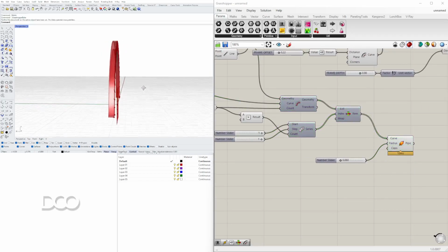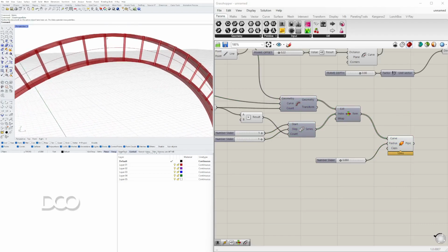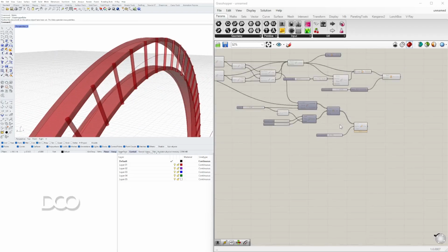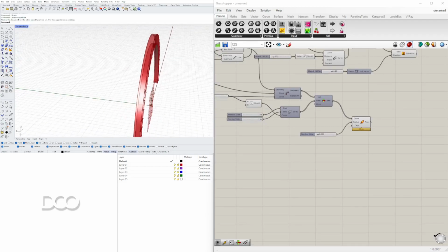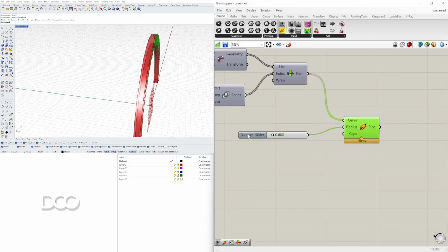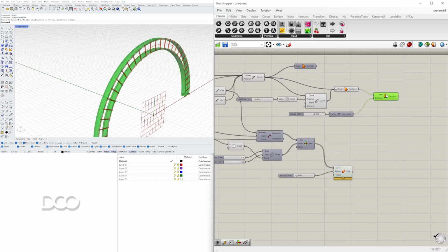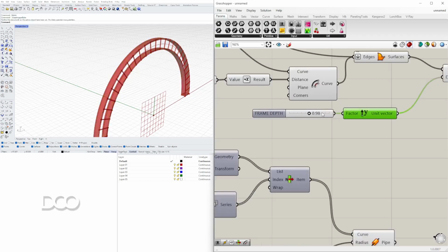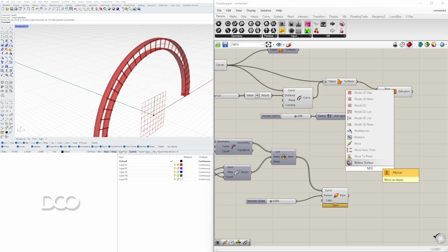Now with the pipes, they're all the way out here in the front, which is cool, but what happens is it technically doesn't work because we're all the way to the outside. So we need to move it in the y direction by the same amount as the pipe or more. So we'll just center it, and let me show you how. Since this was extruded in the y direction by 0.98, then we need to move this in the y direction by half of that. So we'll bring in a move component.